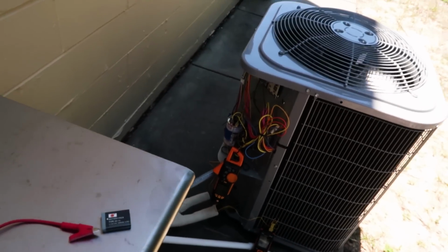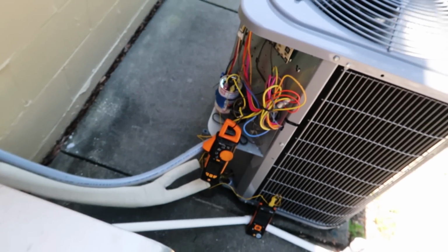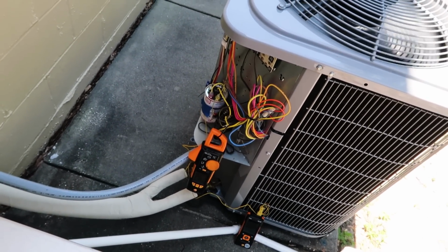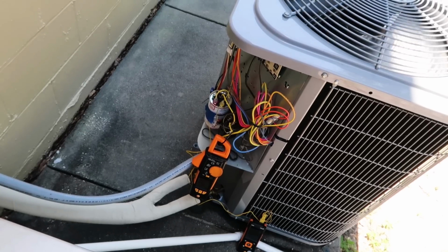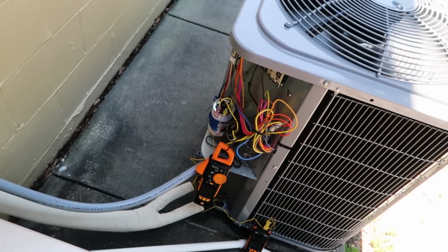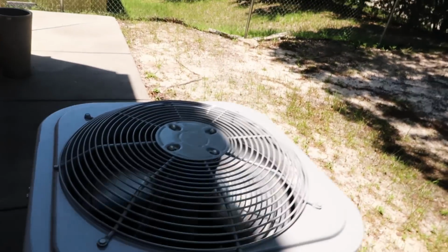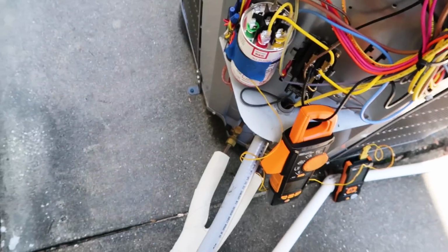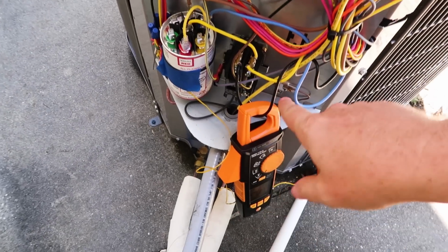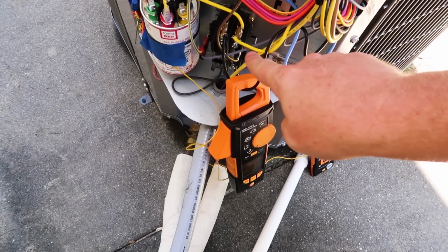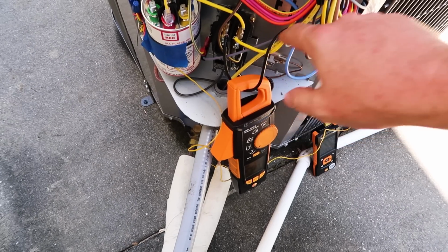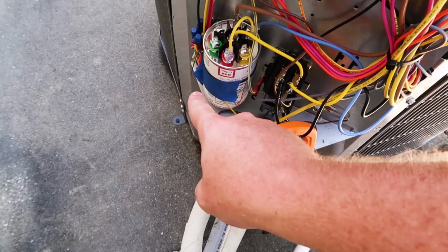In some cases, you're going to notice that your run wire is connected not back to the contactor, but actually back to the capacitor. So in some cases, your run winding isn't going to go to the contactor, it's going to go to the capacitor, and then the capacitor acts as the junction point. In that case, you will get additional heat because it's using the capacitor as a connection point for run. In this application here, your run winding goes right back from the contactor to the compressor, so any heat that's built up is going to be built up through here. It's not going to go to the capacitor at all.